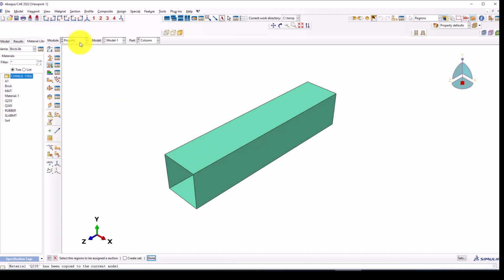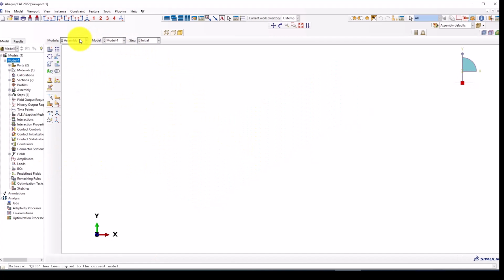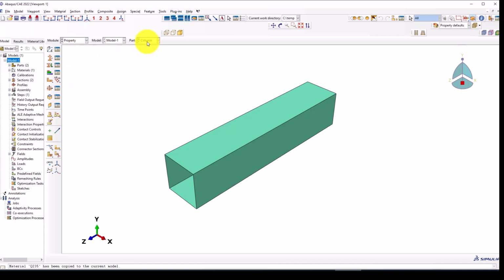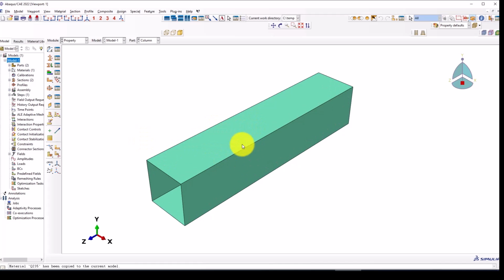Now it's okay. We created both materials, and before going to the assembly, I want to create some partitions for the column, because during the meshing and the contact there will be some distortion later in that joint. So I want to prevent that distortion and also some non-convergence. So it's better to create some partitions and create specific lines which pass through the other elements.